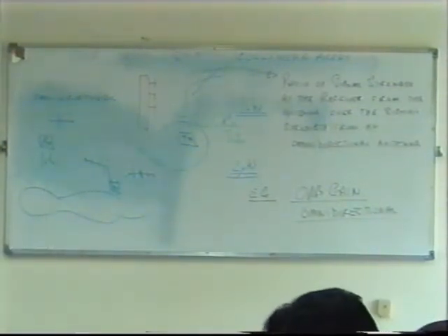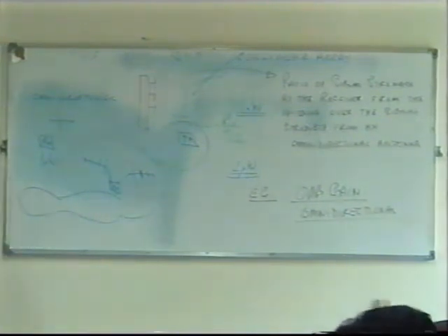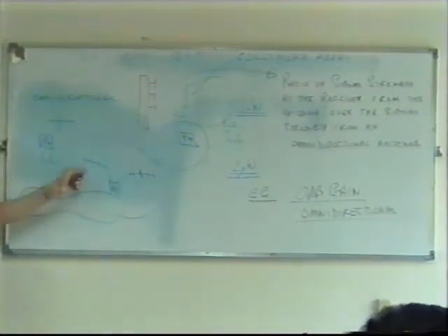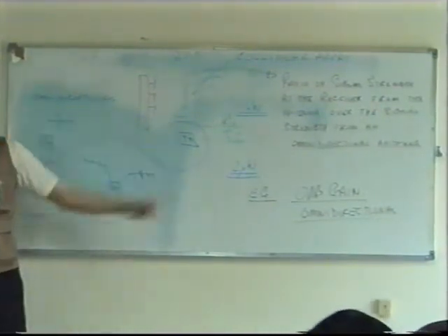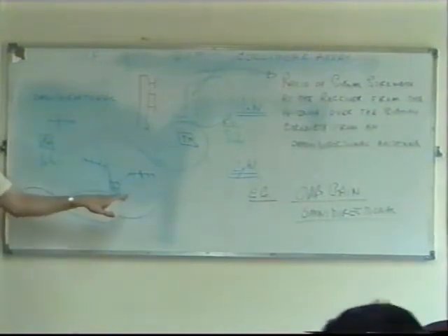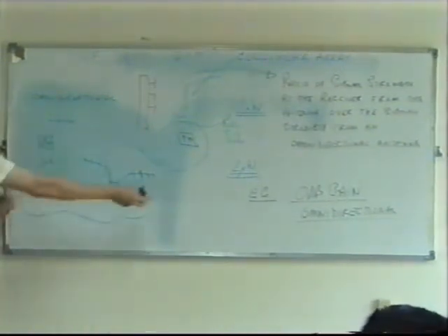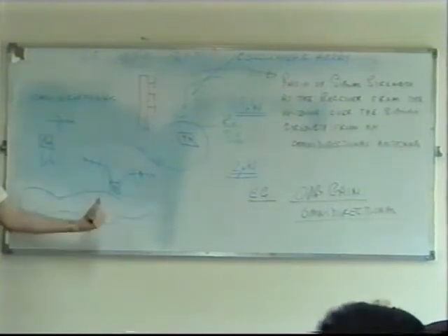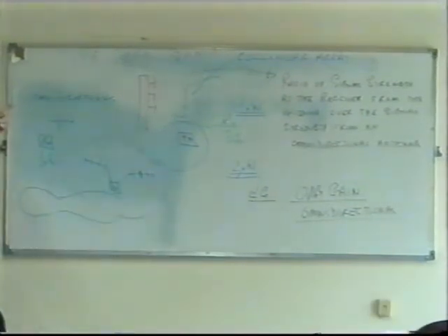Not losing power? Well, compared to using one, the antenna gain of both of them is less. If you use just one and transmit in just one direction, you might get an antenna gain of, let's say, 15 dB. But if you use two of them, same transmitter, same power, it's half power going to each one, isn't it? So you've immediately reduced the antenna gain by 3 dB, because you cannot get the same power from each antenna if you've just got the same power in the transmitter. It's got to divide it between two.